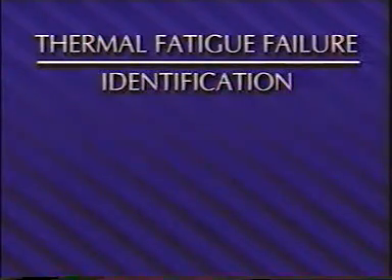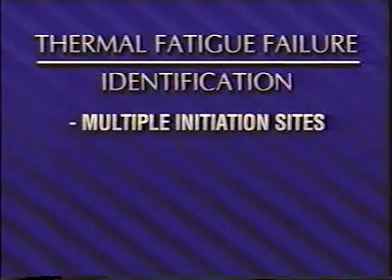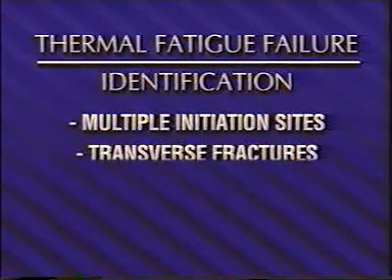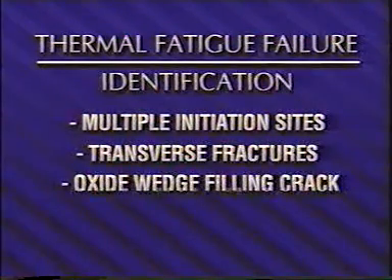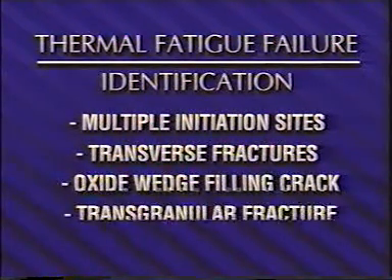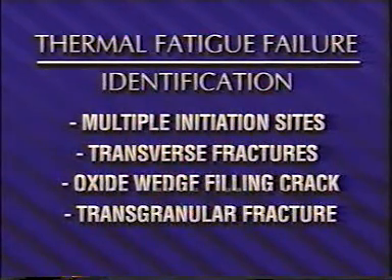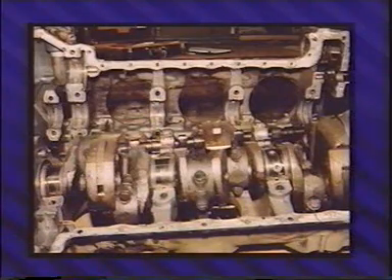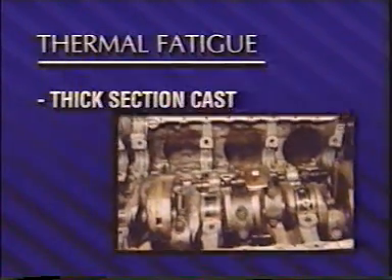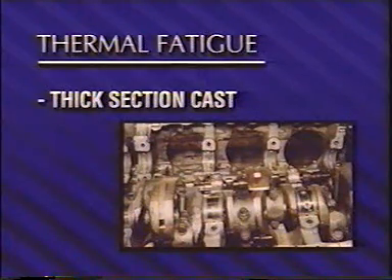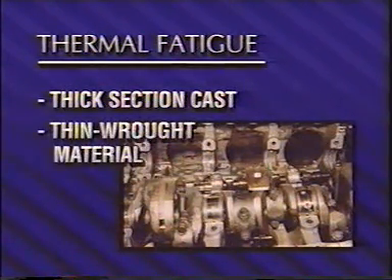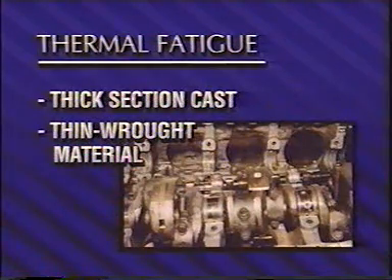Low-cycle thermal fatigue failures can be identified by multiple initiation sites that join randomly by edge sliding to form the main crack, transverse fractures, an oxide wedge filling the crack, and transgranular fracture. True thermal fatigue occurs in such components as internal combustion engines, where thick-section cast materials are used. Thermal fatigue also occurs in appliances and heat exchangers, where thin wrought material is used.